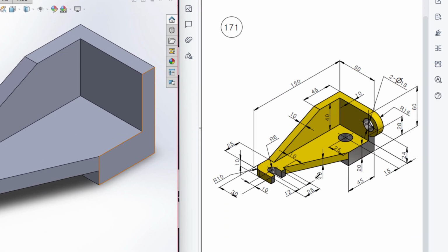Now let's go back to our sketch. In our sketch we can see we have another cut here, and for drawing this cut, first of all I'll draw a center line here, and this center line has a dimension of 10 unit. Then we can see the total distance is 12 units. Then I'll offset it to 6 unit this side and offset it to 6 unit in the other side. Then I will use the capping to draw this arc. Okay, then I will extrude cut this portion.